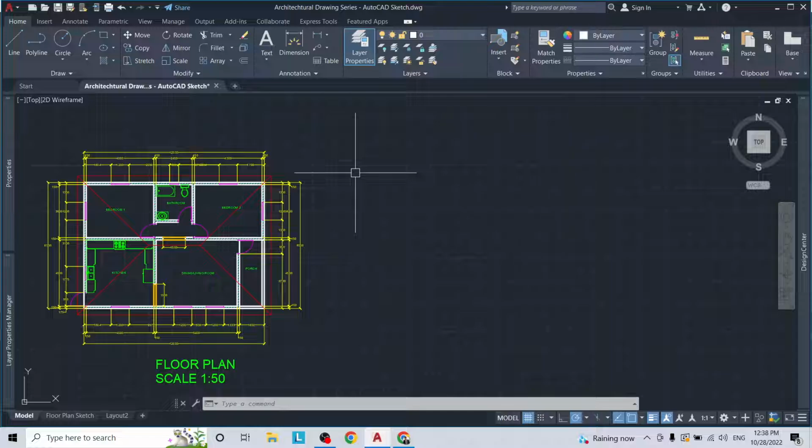So the building can be divided into two parts, the part above ground and then the part beneath the ground level. The part above the ground is called the superstructure. That's your walls, your windows, your roof, all of these things. And then the part that is beneath the ground level is what we call the substructure, and that is our foundation, which is comprised of our foundation wall and our footing and all of the reinforcements, the steel that is placed within them.